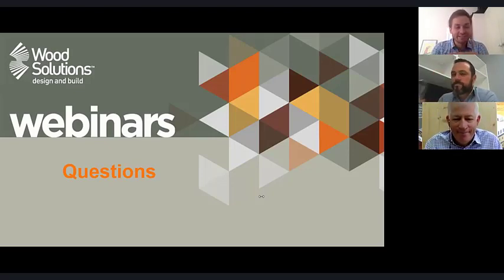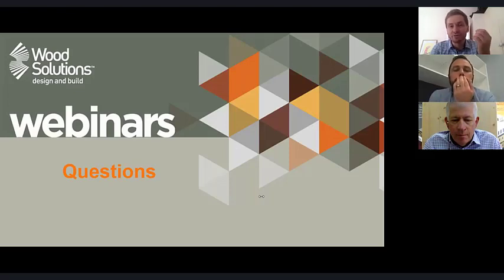You need to think about that. It's going to change on every different connection joint type, but you'll find that locally there's enough ductility generally in those connections to move. It's more of, sort of, level to level that you have these challenges, rather than across individual joints, so to speak. Things like joint closure is going to happen anyway, but you're talking about typically in the order of 0.5 to 1 millimetre for those.